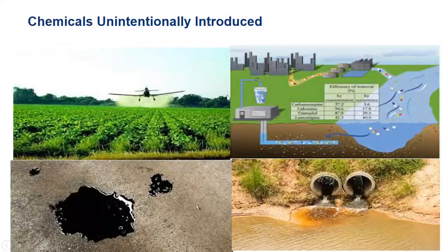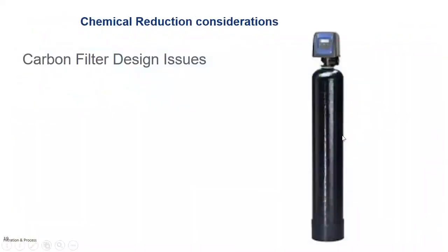chemicals represented in this picture, all of this stuff, pesticides, herbicides, pharmaceuticals, every individual pharmaceutical, every industrial pollutant, all this waste is all removed by activated carbon at different contact times based on its individual chemistry. So we use flow rate and water analysis to understand what we're going to remove so we can determine how much contact time we need with our activated carbon.